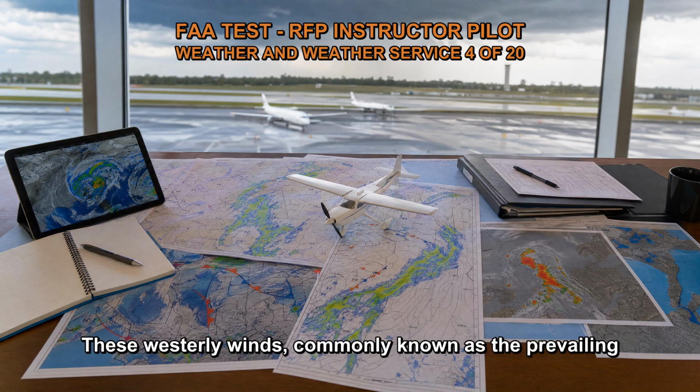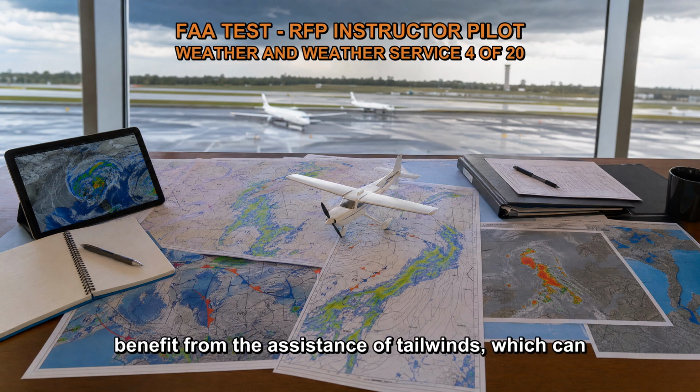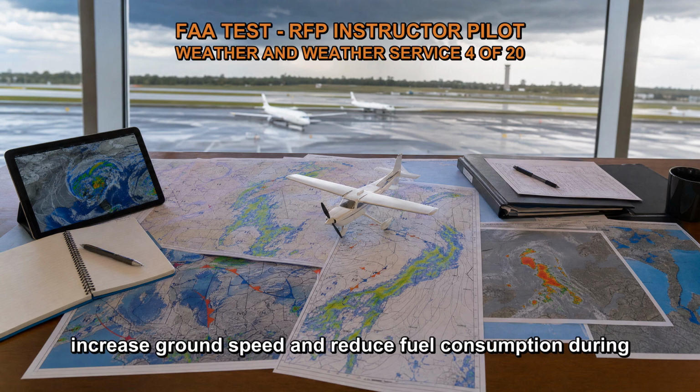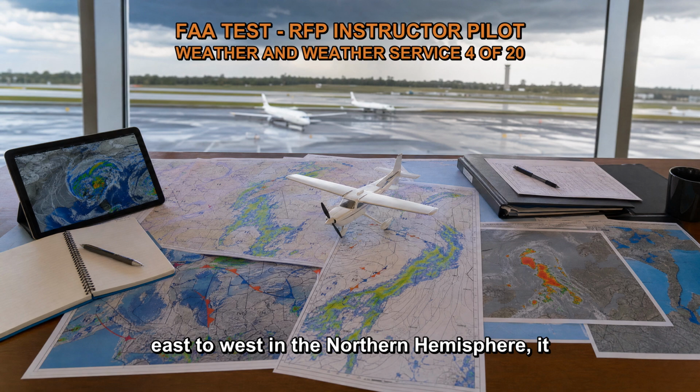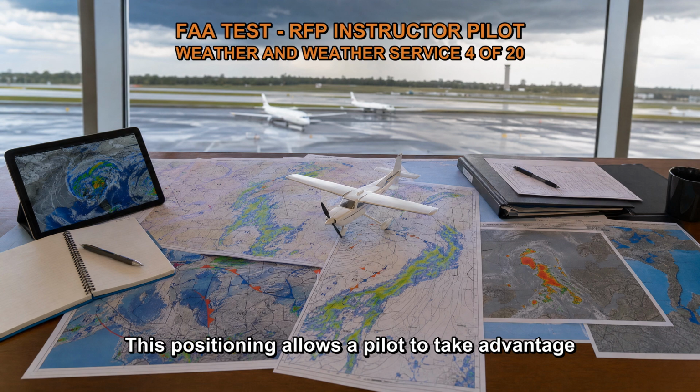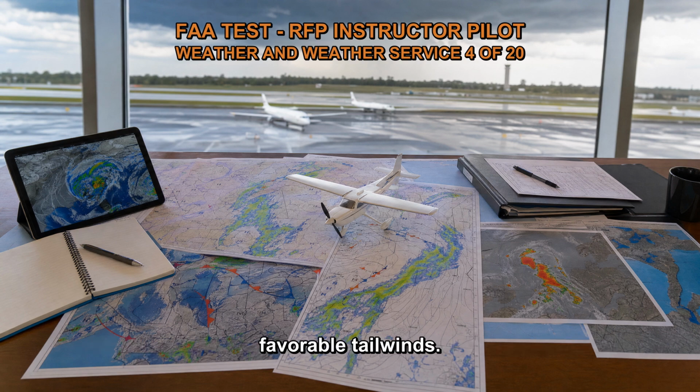These westerly winds, commonly known as the prevailing westerlies, are the primary wind belt in the middle latitudes of the Northern Hemisphere. By flying in this zone, a pilot can benefit from the assistance of tailwinds, which can increase ground speed and reduce fuel consumption during an east-to-west flight. In summary, when making a long-distance flight from east to west in the Northern Hemisphere, it is generally favorable to fly to the south of a high-pressure system and to the north of a low-pressure system. This positioning allows a pilot to take advantage of the prevailing westerly winds and potentially encounter favorable tailwinds.